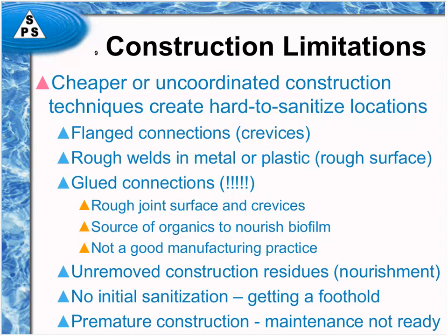I've seen very commonly the construction be completed well before the owner of the water system was ready to take it on. They didn't have their maintenance procedures yet. They weren't ready to validate yet, and so here the water system sits wet, often not even circulating, and growing biofilm like crazy until the owner of the water system finally gets around to starting the maintenance. And frankly, by the time they start that maintenance, it may be too late to get ahead of the biofilm that's already grown.